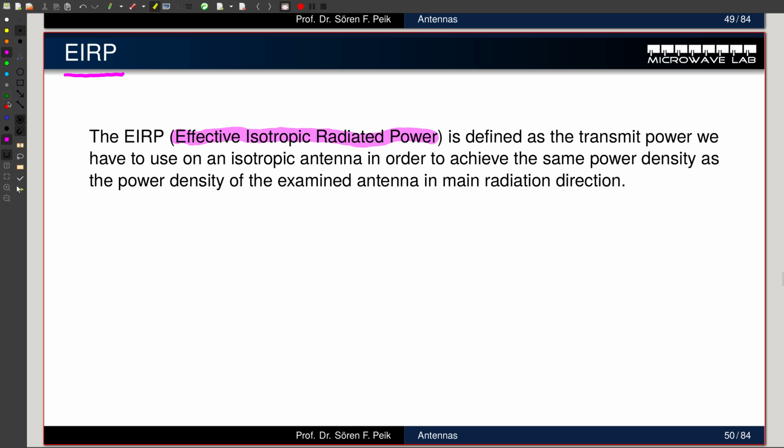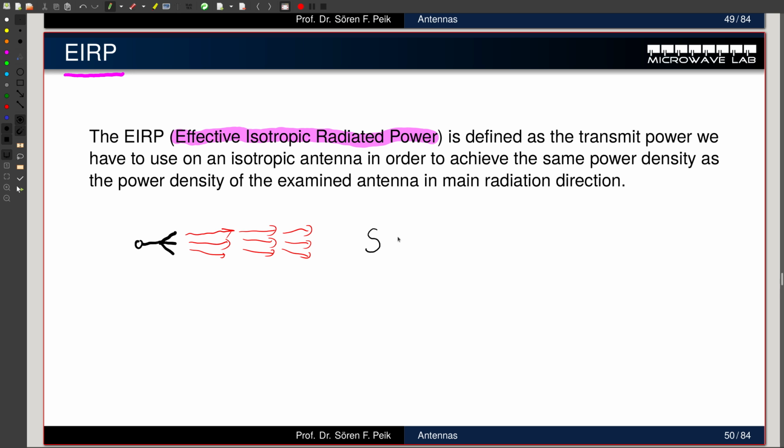And the idea is the following, and I hope I get the explanation here. When I have one antenna that radiates mostly in one direction, and that's something I forgot to mention on my slides, my received power flux density S is the amount of power flux generated by an isotropic antenna, P over 4 pi r squared. Here's my P transmit somewhere.